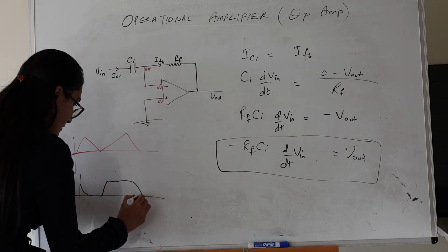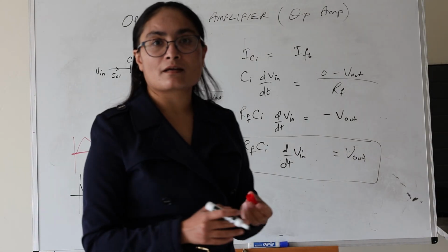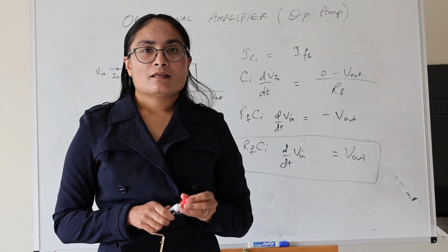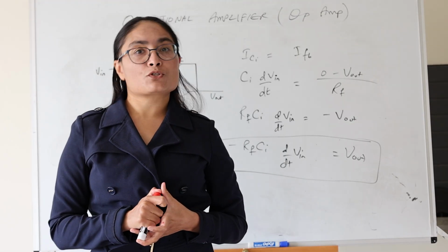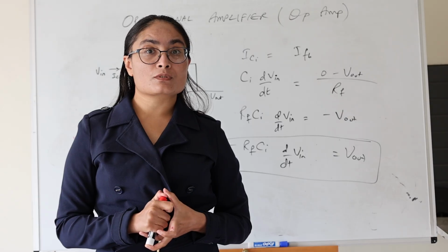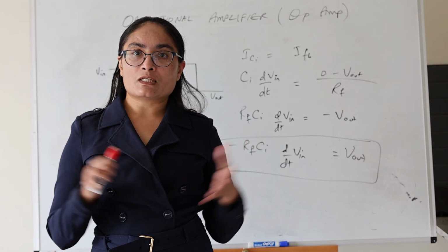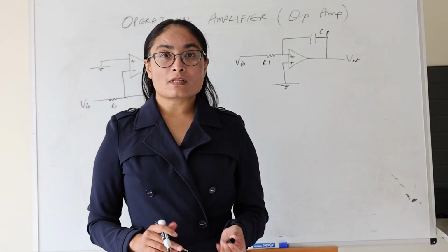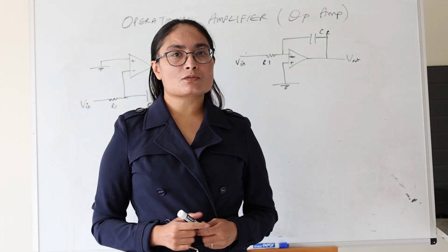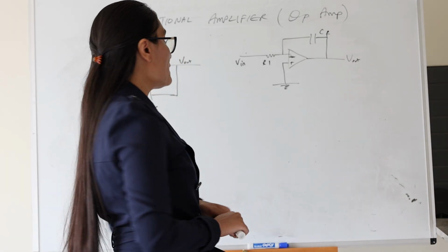Something like that. So that's a use case for the differential amplifier. Now, since we can do the differentiation, you might wonder that we should also be able to use op-amps to do integral operation, and you actually can. So let's take a look at the integral op-amp. For the integral op-amp, we also need to introduce a capacitor similar to how we had for the differentiator.